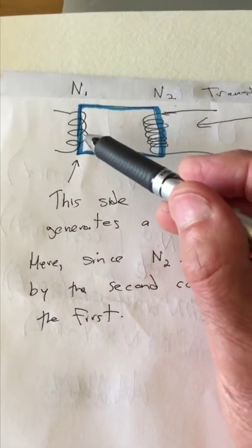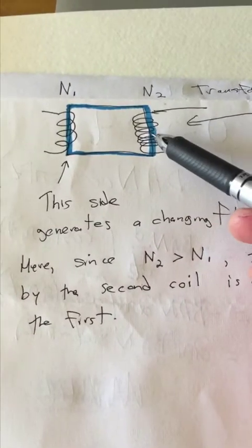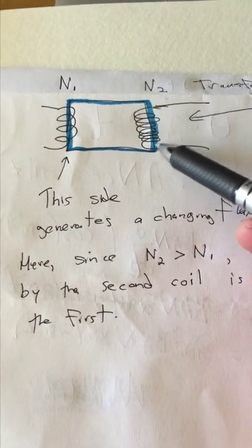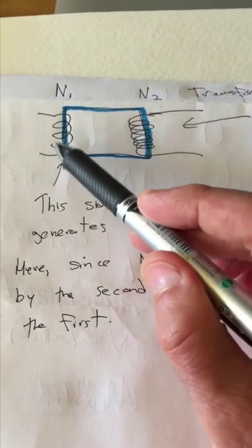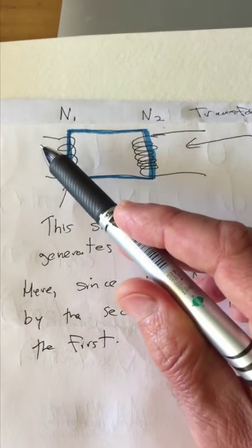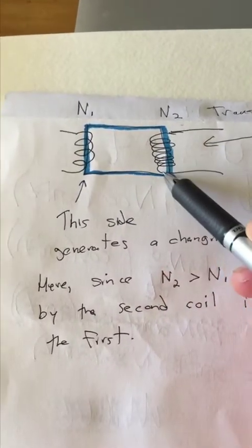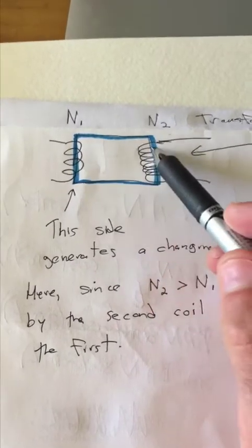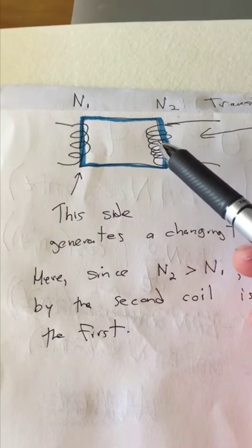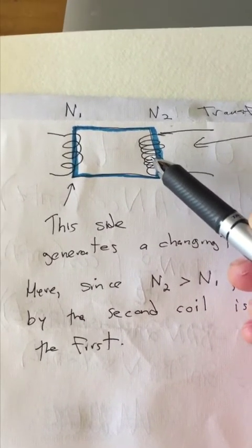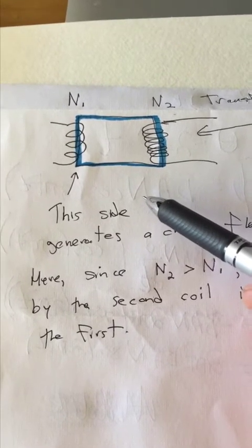In this case, if you have a voltage, for instance, of 2 volts of AC voltage here, and you have twice the number of coils here, then you'll have 4 volts here, but half the AC current that was passing through here as compared to here. So one way to think about it is getting the voltage in this coil to another coil, but it's going to be a different voltage. You're able to transfer through this metal ring and change what the voltage level is. Isn't that amazing that we can do that? There are reasons for that I'll describe in a subsequent video, and that I also describe in the PowerPoint slides.